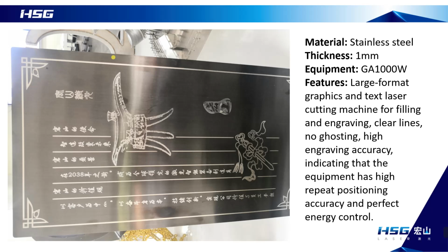And the laser is about 0.1mm in diameter when it's focused. So you need to hit that width continuously. We can see that the lines are very straight. There is no individual prominent or bending phenomenon. The repeated positioning accuracy of this machine is relatively high.